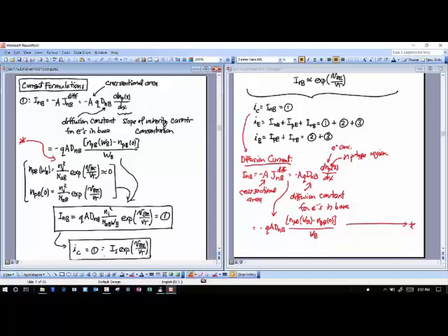But I'm going to approximately say that that's equal to this, and so I sub S times E to this. Right, I'm going to shorthand this as I sub S times E to that. I sub S is a saturation current, and you notice that I sub S is merely that. Okay? So with this physics that I've applied, I now have an equation by which I can calculate I sub S.